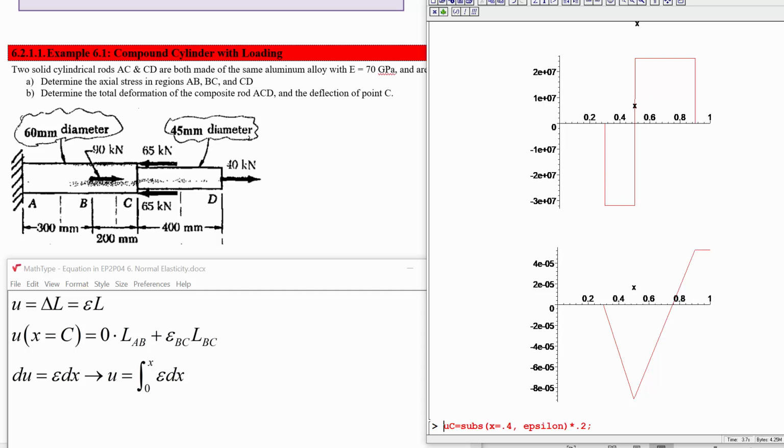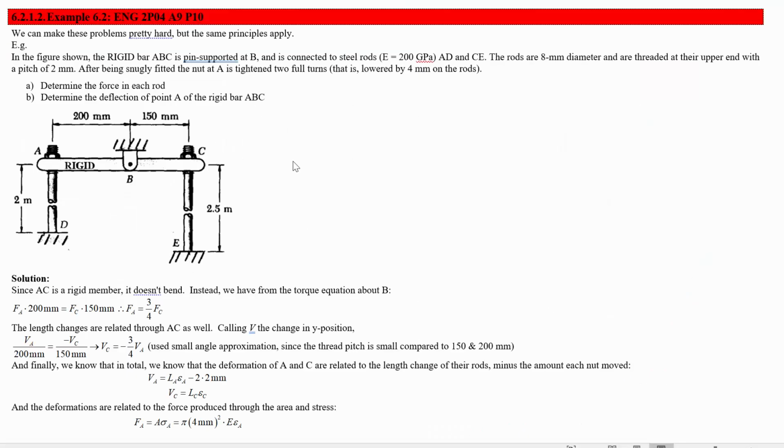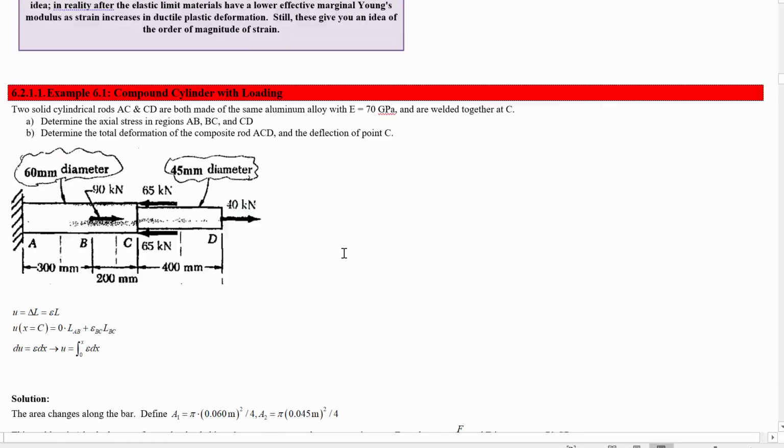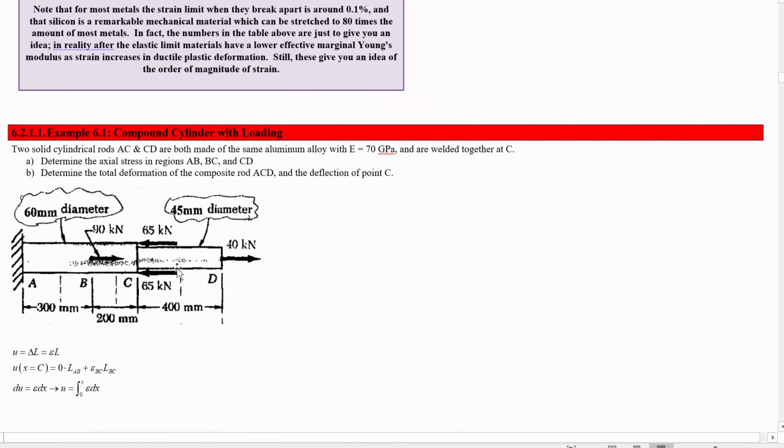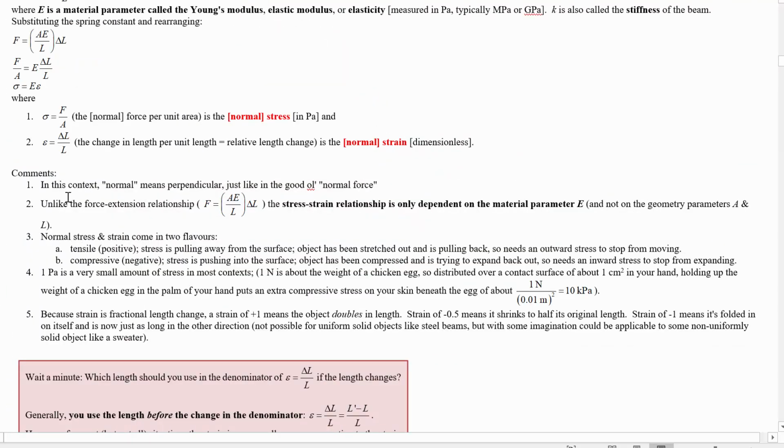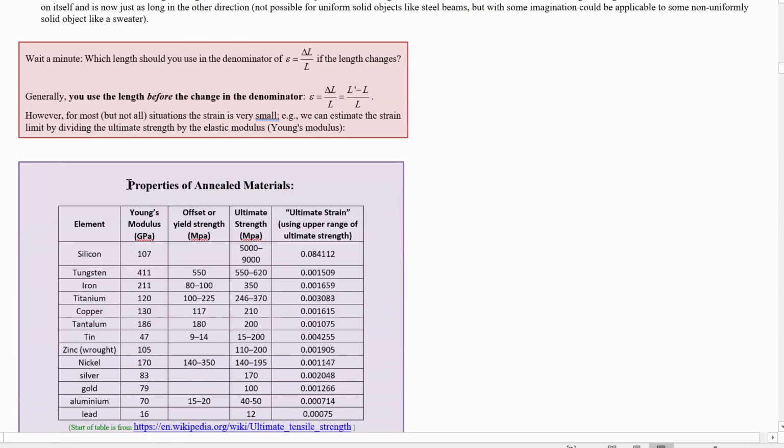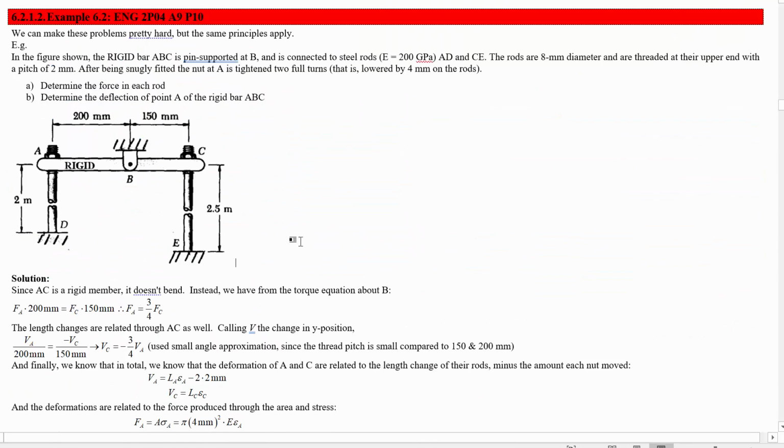So this same principle, this idea of relating the stress internally and the strain and the force via the Hooke's law equation, is going to allow us to now set up problems like this, where we have a rigid bar and have a support over here and another support over here, and figure out how the forces are related in more complicated setups like this one.